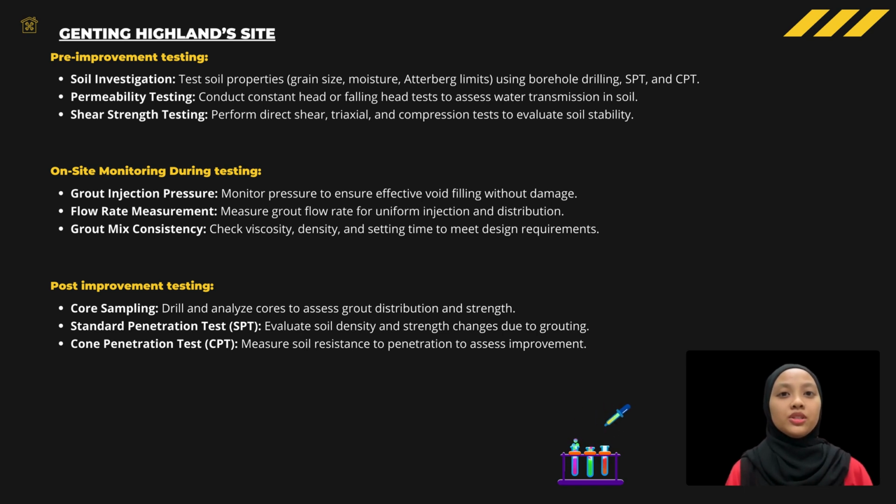For on-site monitoring during testing, there is ground injection pressure, monitoring pressure to ensure effective void filling without damage. Other than that, flow rate measurement to measure grout flow rate for uniform injection and distribution. Grout mix consistency is also checked for viscosity, density, and setting time to meet design requirements.